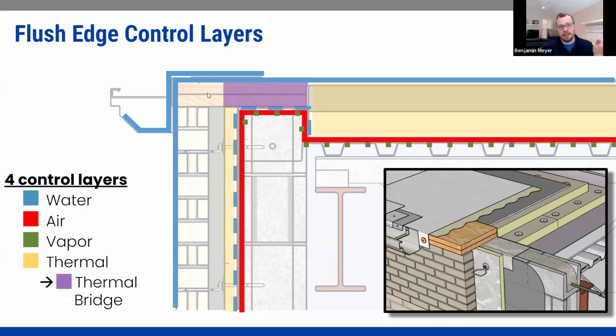And technically that's not insulation, but if you look at the new thermal bridging requirements in ASHRAE 90.1, wood is considered a low enough thermal conductivity that you're not going to get a lot of R value out of it, but it's also not letting a lot of energy escape. So wood is kind of that crossover material that's between insulation and not.